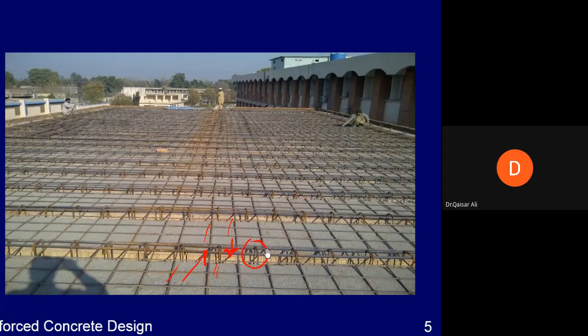This reinforcement makes the slab and beam monolithic. Okay, you can also see the top horizontal reinforcement of the beam is placed actually inside the slab. This is because this part is part of the slab. So the reinforcement of the beam is actually such that part of the stirrup will be inside the slab, and the top reinforcement of the beam will be passing through the slab actually. And now you look at the slab reinforcement, the slab reinforcement is passing through the beam.